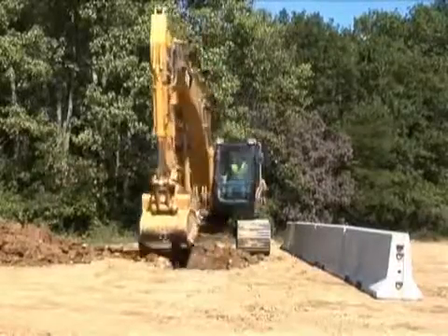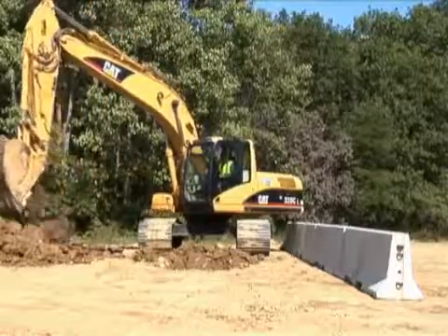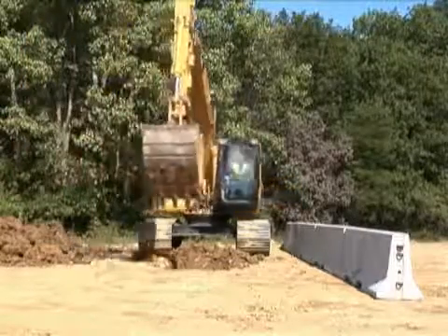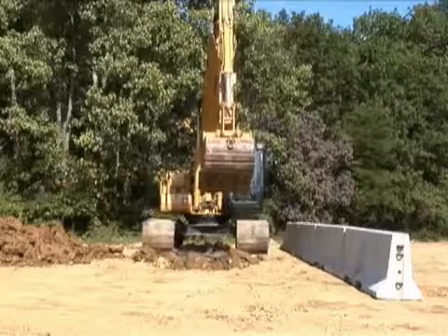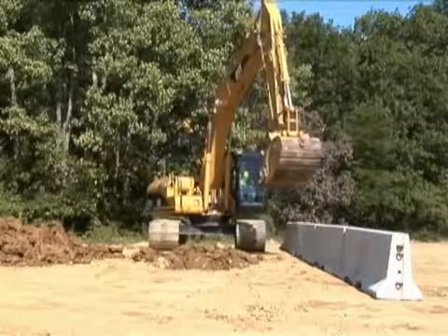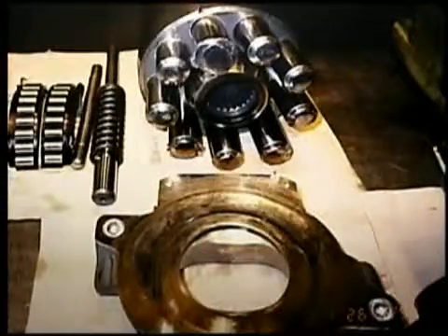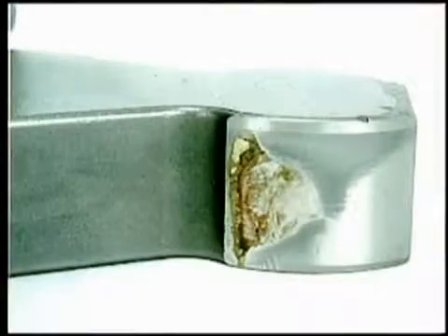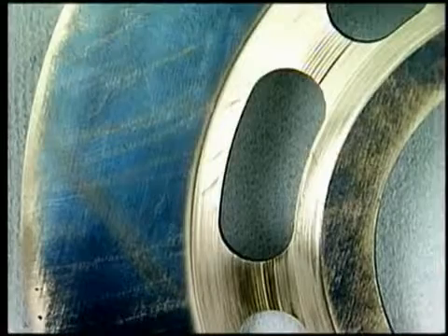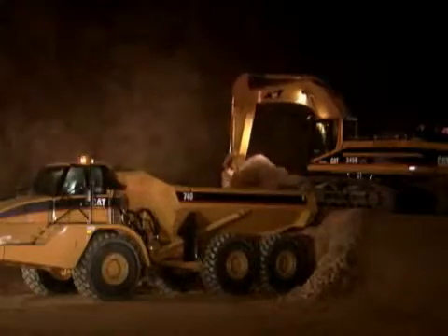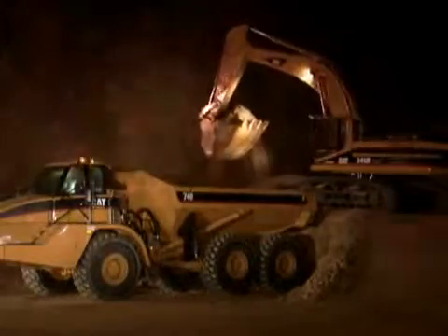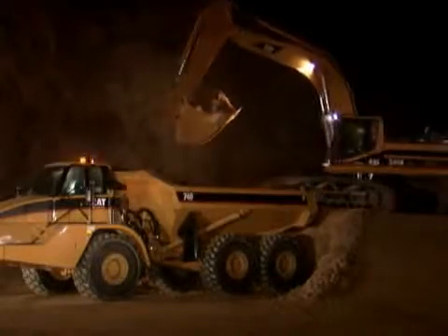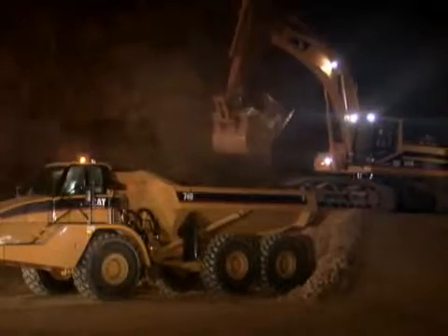This is just a small segment of the hundreds of feet of hydraulic hose in this excavator. In addition to carrying hydraulic fluid, this hose is also storing and carrying contaminants. This is a piston pump. It's no longer pumping any hydraulic fluid. It failed because of too much contamination. This excavator sits idle and unproductive since an excessive level of contaminants entered the system and went unaddressed.